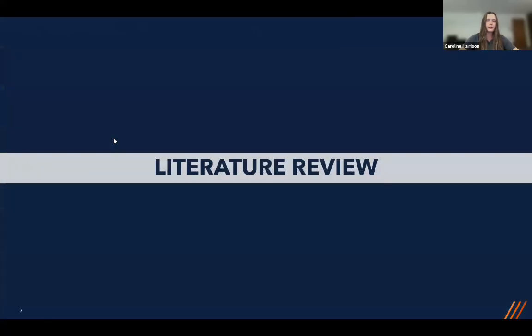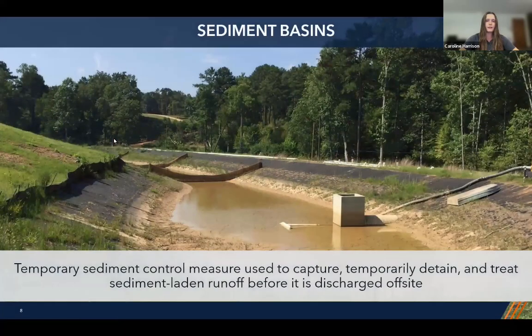Going into some more background here. Sediment basins are temporary structures that are installed on construction sites as a sediment control measure. They're used to capture, temporarily detain, and also treat sediment-laden stormwater before it is eventually discharged off-site. Sediment basins using sediment control systems have been found to remove up to 98% of suspended sediment after rainfall